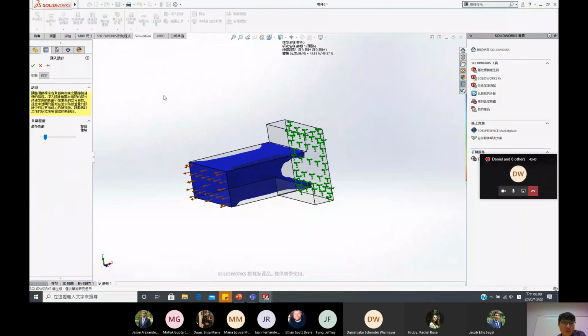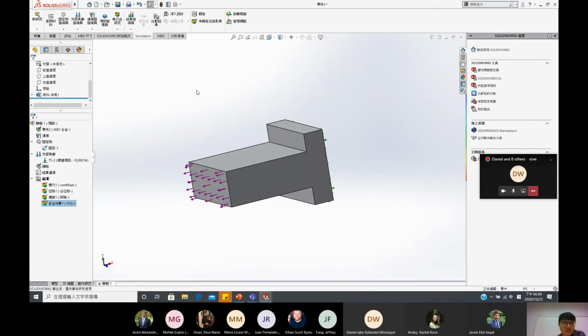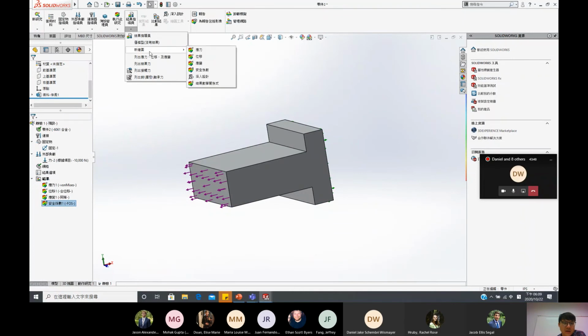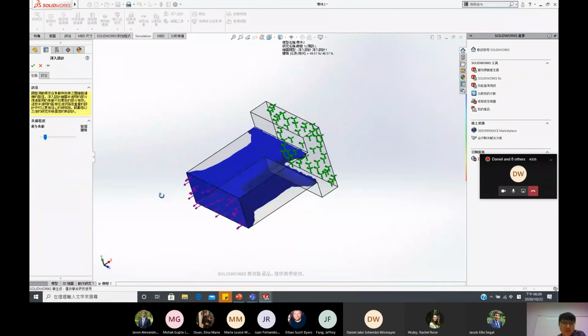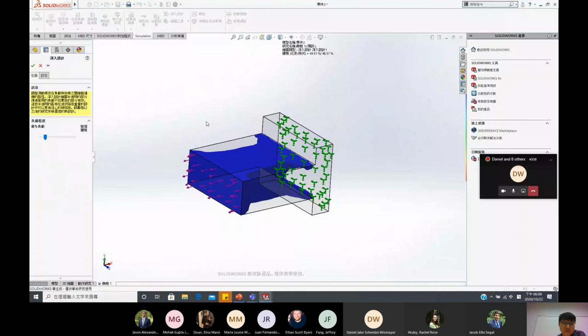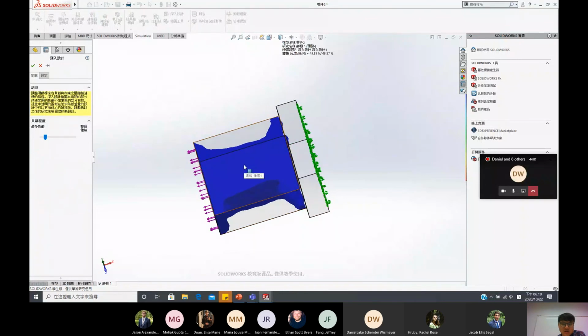What I'd like to show is, let's re-click this. If you go over here, this is basically an optimal design, so I'm going to click that. It generates the color design you see here. When we design things, you can imagine that we want a lightweight part that still has its strength, right? One of the things it does is help you do the calculations to optimize. What material is really unnecessary, that we don't need, but still maintains the strength while a force is applied to it?